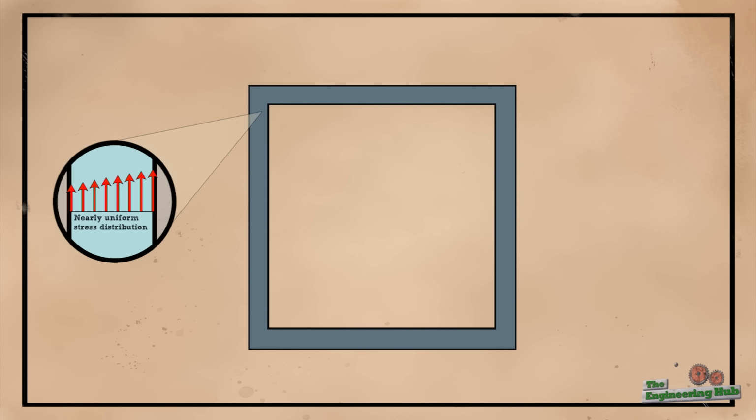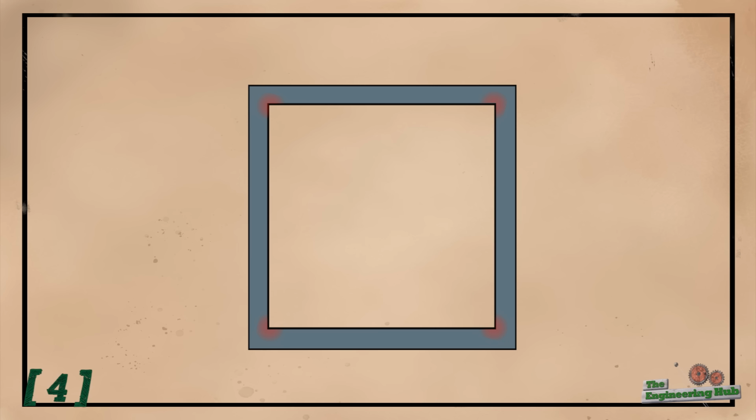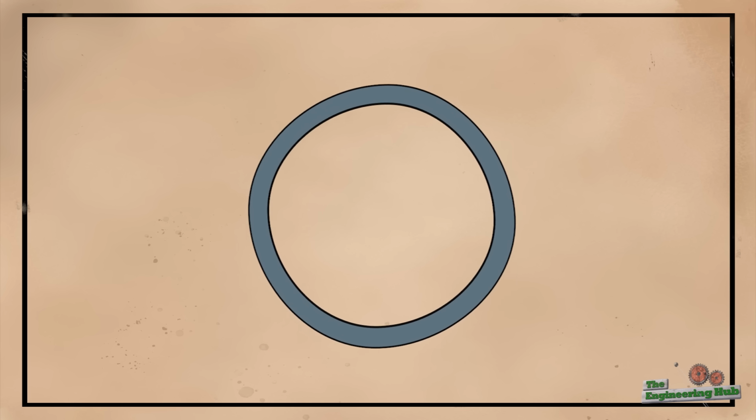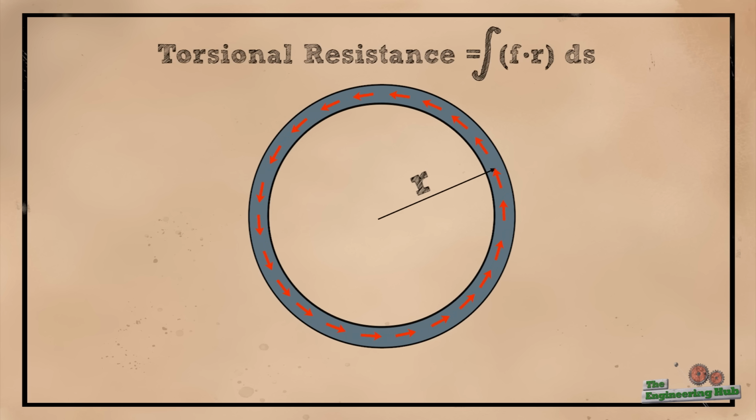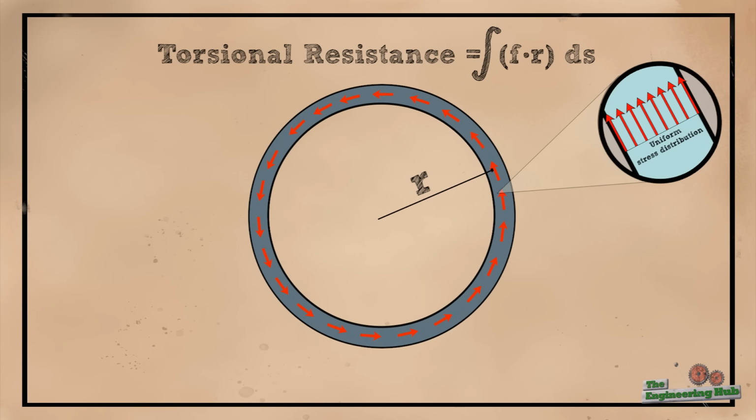An avid watcher might ask, doesn't the corner of the square tube technically cause a discontinuity because of its sharp edge? The answer is yes, sharp corners do cause discontinuity and stresses. One way to make a beam with equivalent area even stronger than we've shown is to make a hollow, circular tube. Now this beam has the most possible continuous, smooth area as far from the center as possible. Now, this shape is optimized for resisting torsion.